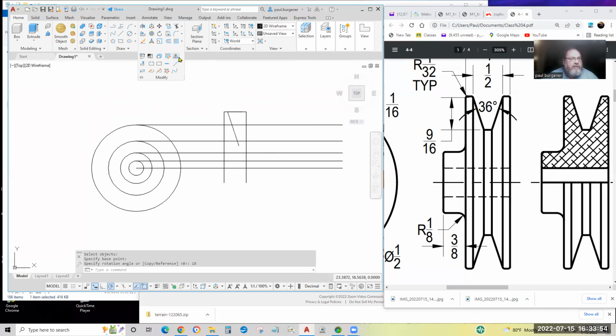I'll drop down and use my old, by the way, I'm on the 3D modeling workspace. This is a level 2 class assignment we did last night. Drop down, I'll do the old 2D mirror command or icon. Select it, hit enter, O-snap at the middle of this guideline, and polar track straight up or down and click enter.